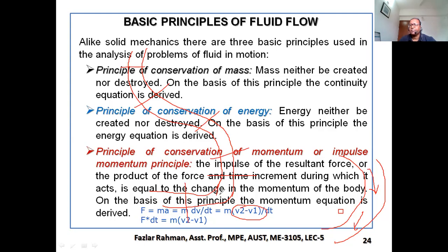So in this area, due to the change of momentum, the fluid will impose some force on the pipe. And you need to make sure that the support of the pipeline can carry that force. Okay. And we'll derive that equation. We'll show you that if there is a change of momentum of the fluid, how we get a force.